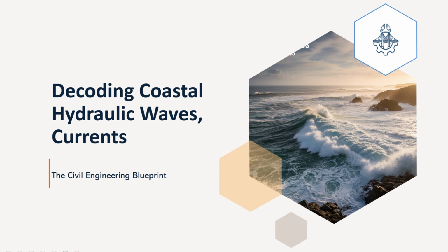And this leads us to a critical engineering parameter, the pressure response function, Kp, which simplifies this analysis for practical use, relating the pressure fluctuation to the surface elevation. Exactly. The pressure response function is defined as Kp = P dynamic / ρg η, where P dynamic is the amplitude of the dynamic pressure fluctuation and η is the surface elevation. Using our theory, this simplifies beautifully to Kp equals cosh k(h+z) over cosh kh.